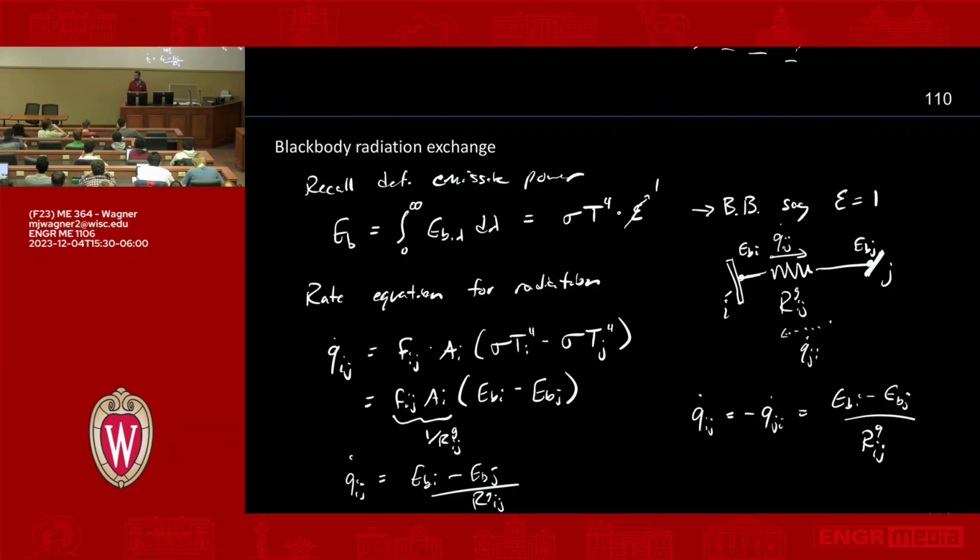Yeah. And will we have geometric resistances combined with thermal resistances? Yeah, it's a really good question. Would you have the geometric and thermal resistances combined in a single network? No, you cannot combine a geometric resistance and a classical conduction or convection thermal resistance. You can't combine them because they have different units, right?